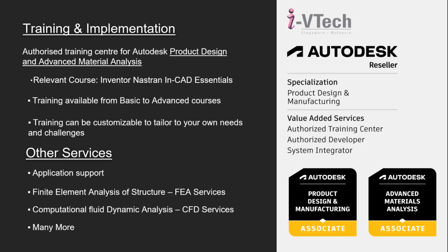Just to add on, if you are using just pure Inventor Professional, what I presented earlier is an add-on analysis capability, which is only available in the PDMC collections, which is Nastran In-CAD. So if you are just using Inventor Professional, you won't be able to perform anything more than static structure and vibration. Like what Syed presented at the beginning, you can do much more than what Inventor Professional can do in terms of analysis. You can go up to linear, non-linear, static, vibration, heat transfer, and drop test, and so on and so forth.